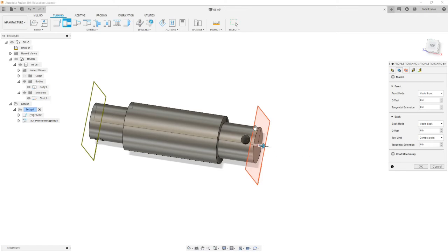Now in the geometry, we've already machined off the face, and then when we come back and part off the part, we want clearance for the parting tool. The parting tool is 118 thousandths wide, so we're going to overshoot by about 1/8 inch to give it a little bit of extra clearance. On this side, we'll probably overshoot just a little bit, just to make sure that if there's any registration difference in the tools, that we don't start the cut right inside the work.